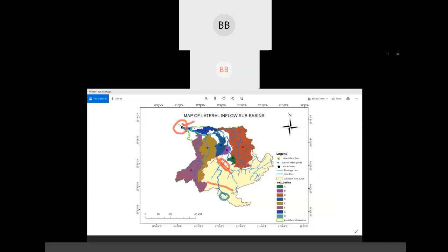It depends on you, you take here or here, doesn't matter. Then you take the RL of this portion where you require to find the slope. You take tan theta, which gives you the slope, so you will get the appropriate one, not the exact one.